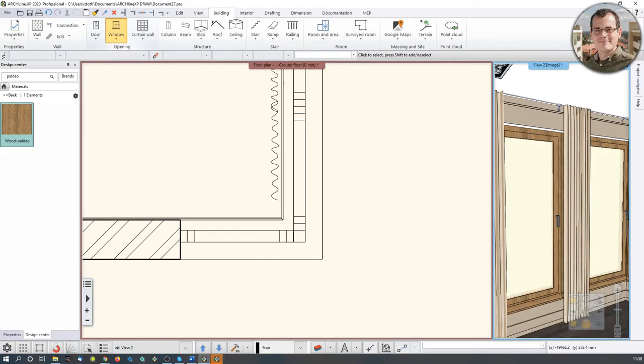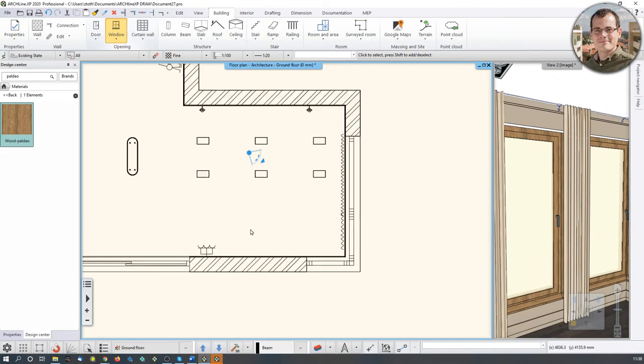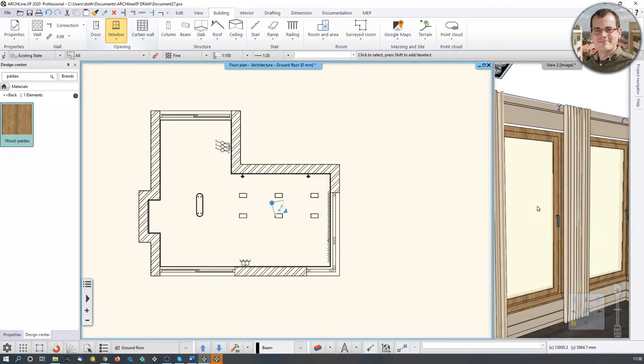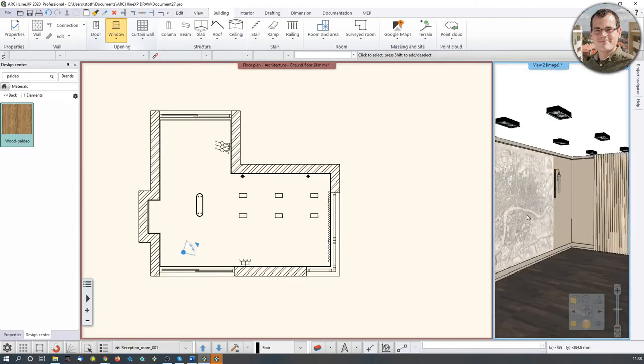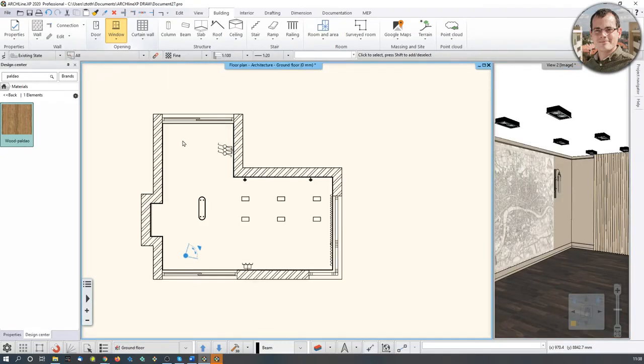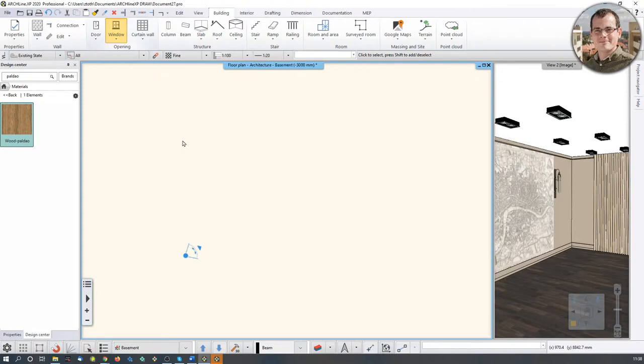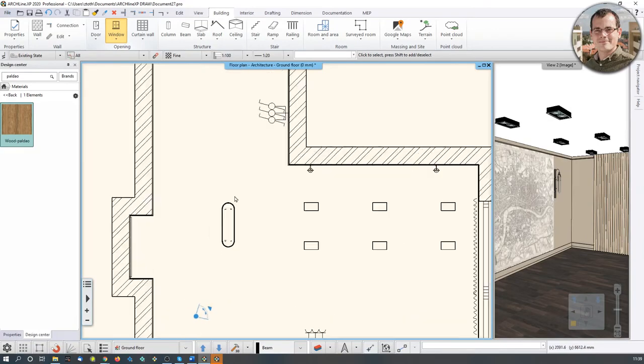Now let's talk about how we furnish this floor plan. This doesn't have that much going on, so let's just find a good view. Oh, by the way, if you use the Page Up and Page Down keys in the 3D, the software navigates between the perspectives. But if you use the same keys in the 2D, it navigates between the floors. Now we only have one floor, so this makes no sense, but I just wanted you to know that if you somehow made the floor plan disappear, there are two things to know. One, double click, because that moves the model back to the view. But if it's still not appearing, just use the Page Up and Page Down keys, and then the model should appear. I think, yeah, here we go.